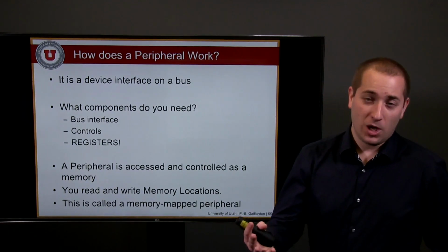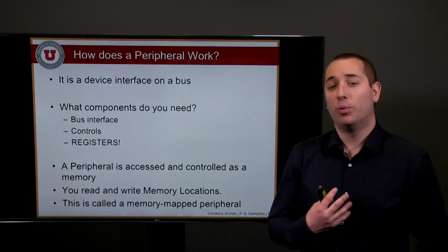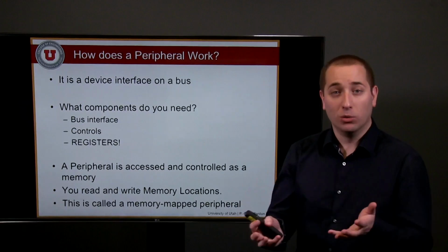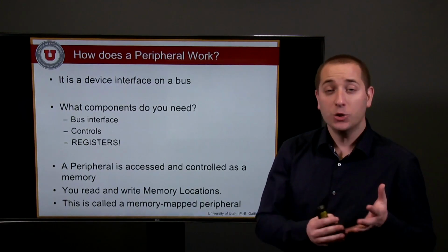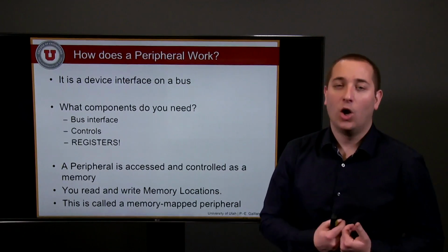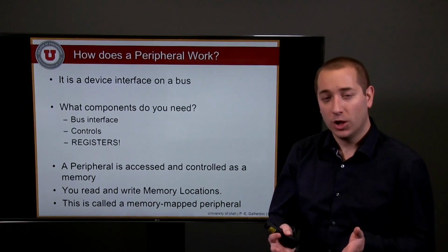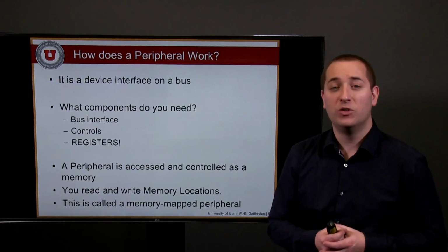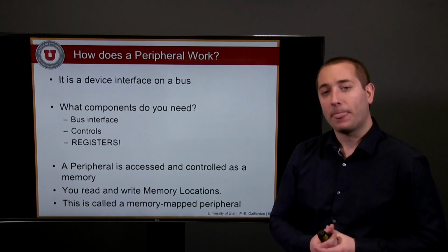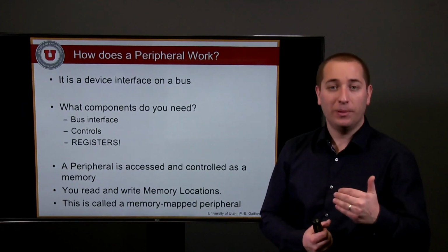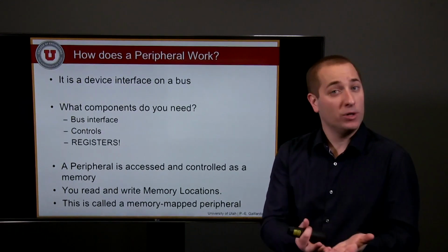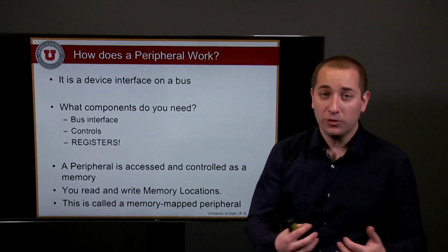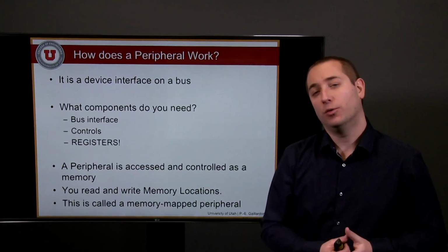Talking about peripherals, the most important question to ask is, how does a peripheral work? A peripheral is a module that does something specific for you. But how do you access it? How do you control it? Usually, you will connect this piece of hardware to your peripheral bus, and it will simply be used as a device interface on your bus. So when you do that, you will simply read and write data into memory spaces, and this memory space is being used as control registers, buffers, input-output buffers, queues, and so on and so forth.